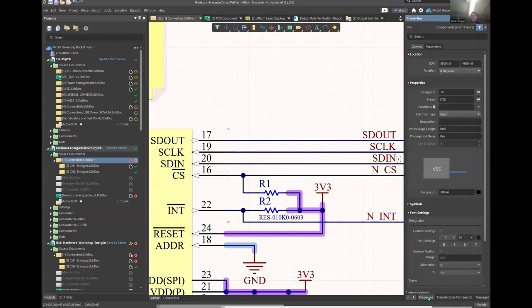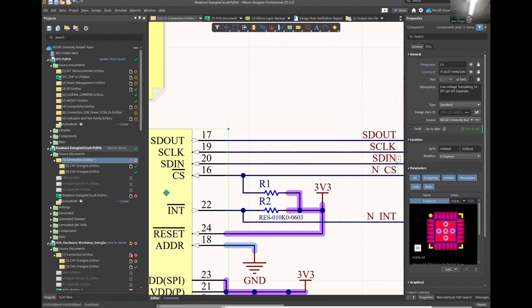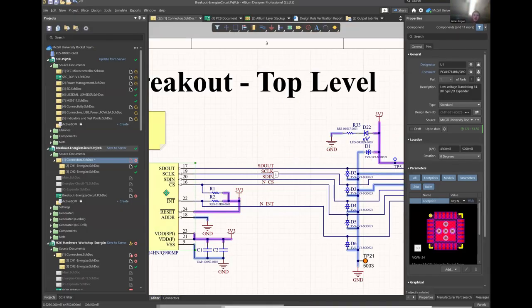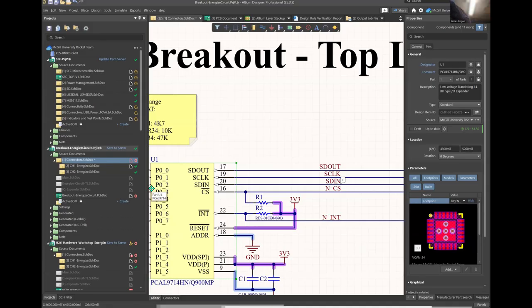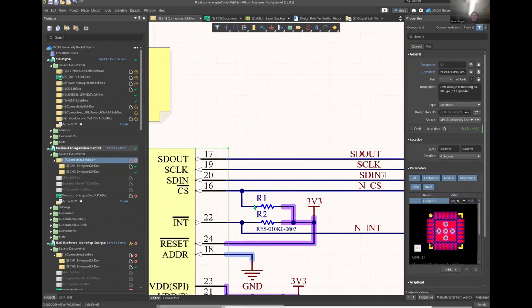What Altium does, which is super useful, is it maps a component and its pins onto a certain layout of copper. So for example, this component here has 24 pins on it, and each one of these pins is, in this case, mapped to one little section of copper along this footprint here. And you can connect these pins up to each other using nets.